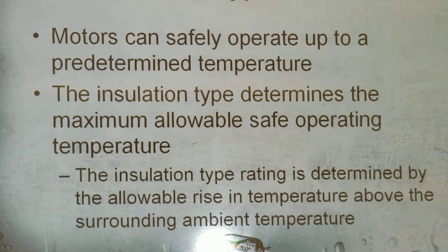Installation type or class. Listen. Motors can safely operate up to a predetermined temperature. The installation type determines the maximum allowed safe operating temperature. The installation type rating is determined by the allowed rise in temperature above the surrounding ambient temperature.